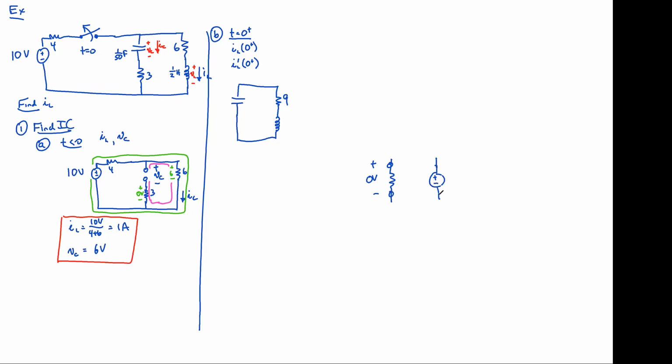Anytime you know what the voltage is across any component, or the current through any component, you can always replace it with the equivalent voltage source or current source. And now what's a 0 volt voltage source? It is a wire. All right, thank you. That makes sense. And so that's the rigorous version. The unrigorous version is, yes, I just ignored it because it was 0 volts. So I know in my head it's a wire, but there it is with the right way to think about it, to justify it, I should say.